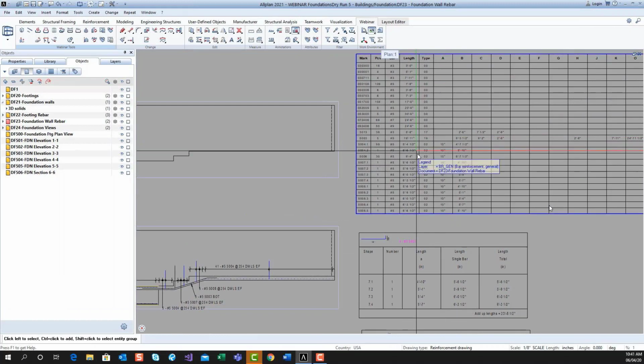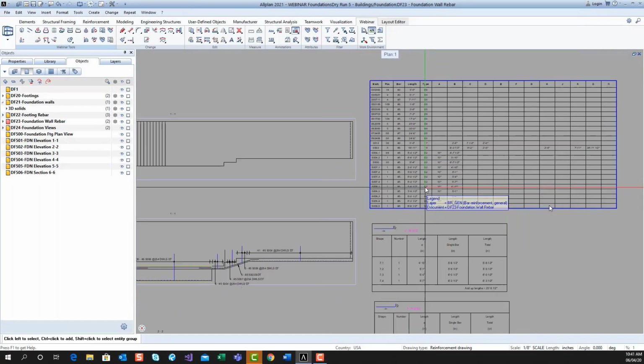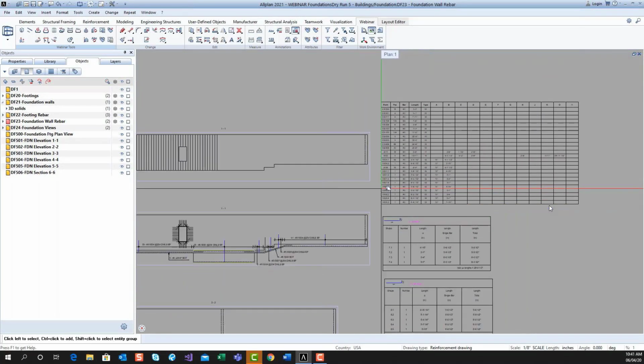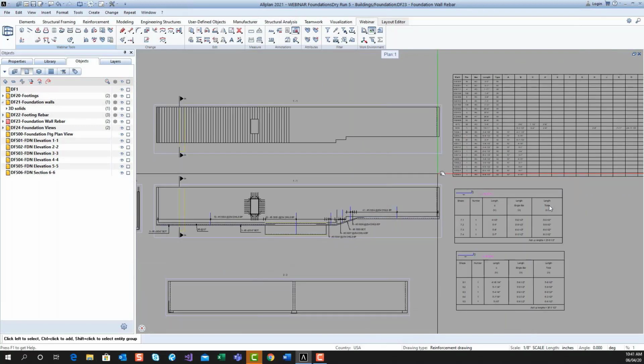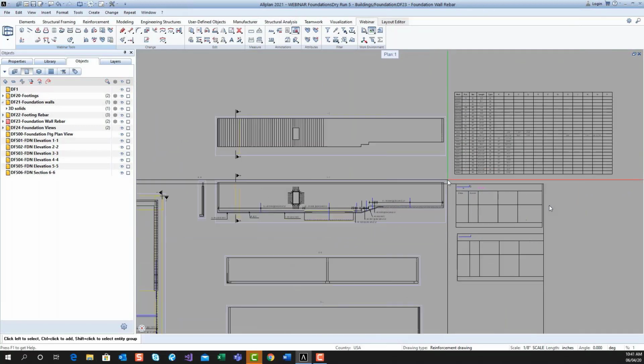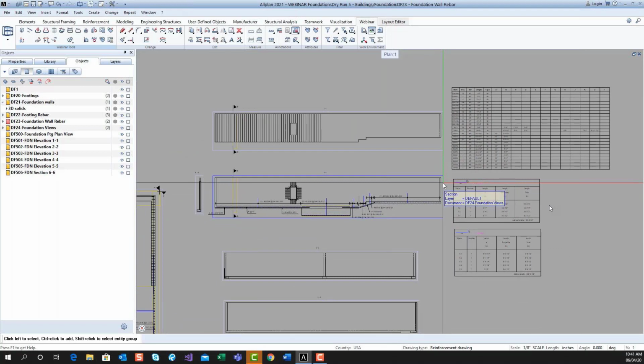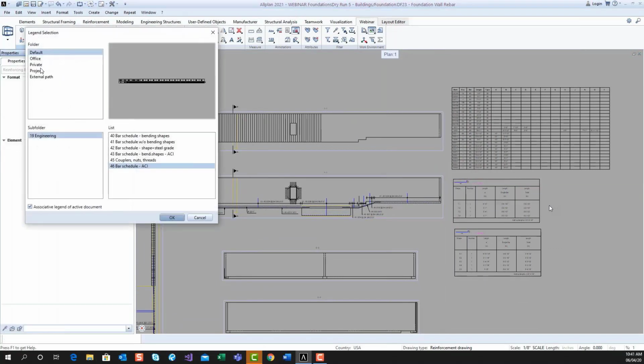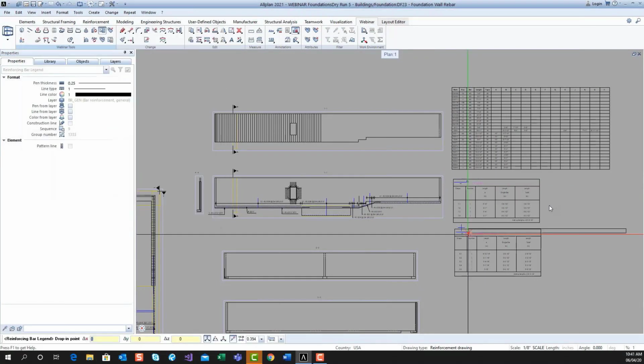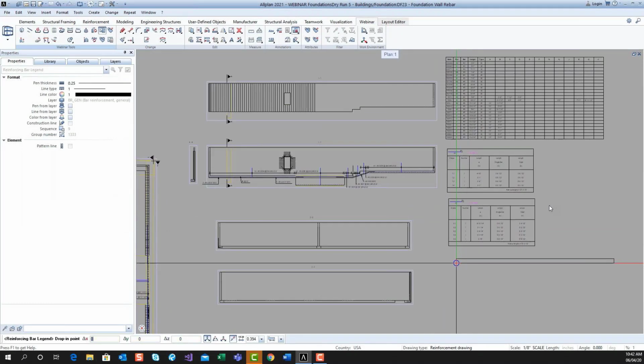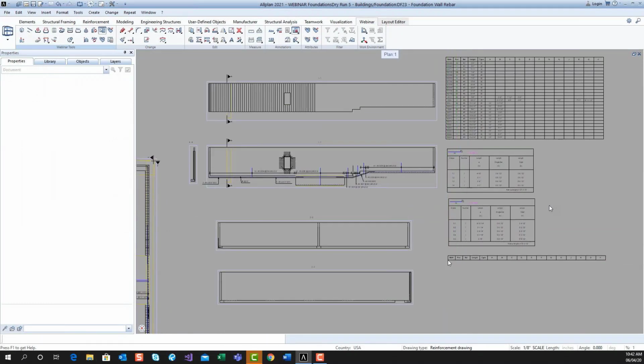I can show you the bar size. There's my ACI shape codes 2.17.0. It shows all the varied bar marks if you want them in that particular list. And I'm also going to show you one I've sort of developed, which is more recognizable to a rebar detailer, which allows for release information. Segregate the bars by releases. So you'll notice as I first bring this in, the bar list is empty. So I'm going to go ahead and place it.